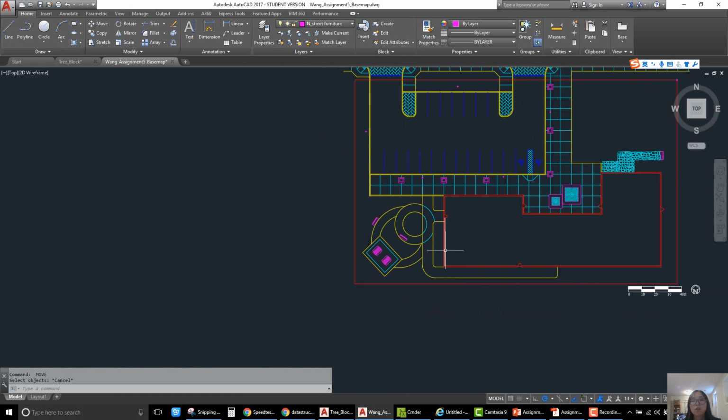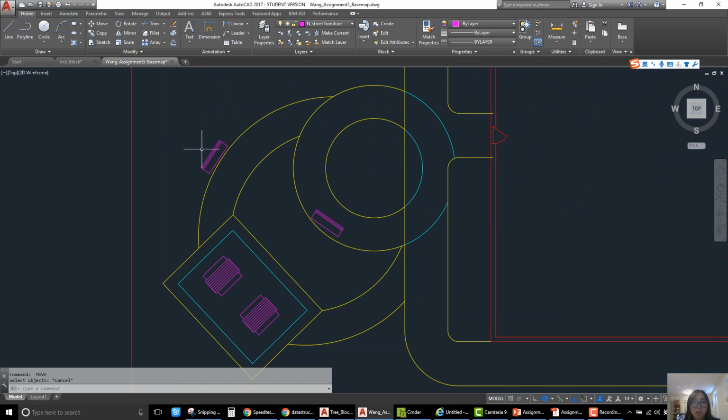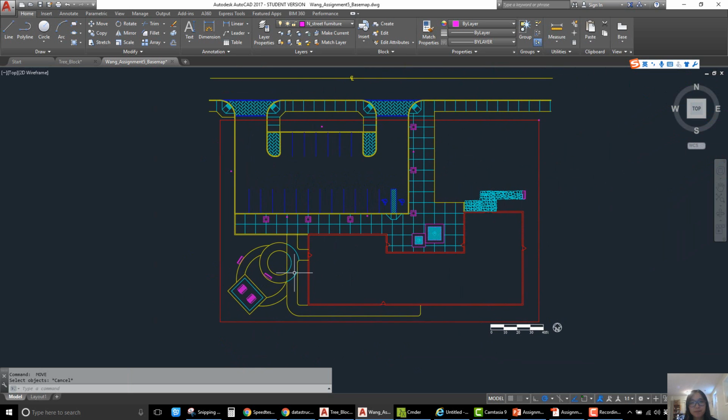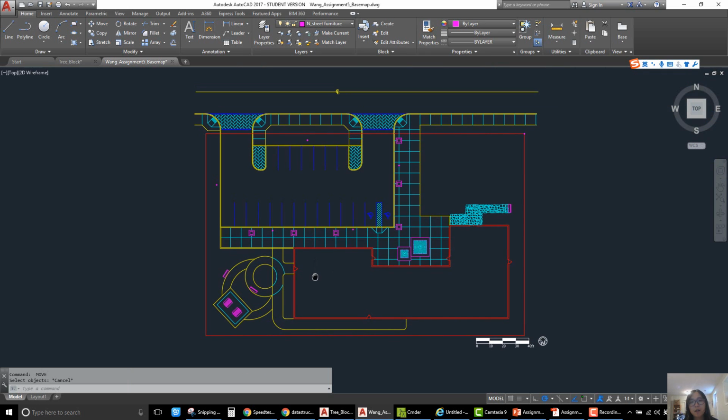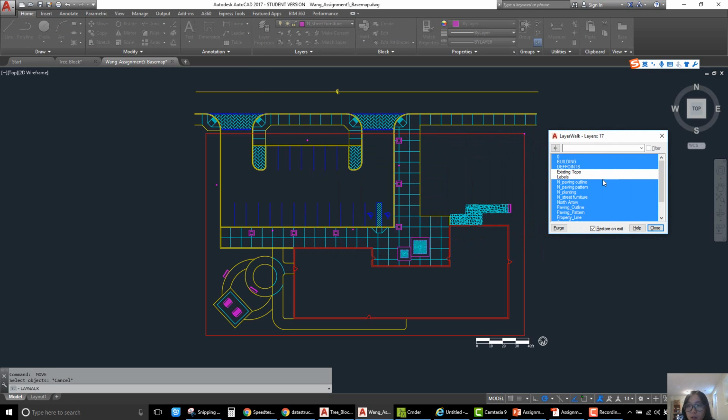For those street furniture pieces, you don't need to have a super accurate location and angle, because they are just furniture. And then I think I have finished all the drawings, and let me check if they were drawn on the correct layer. So I will open the layer dialog by typing lay work, spacebar. Let me see.